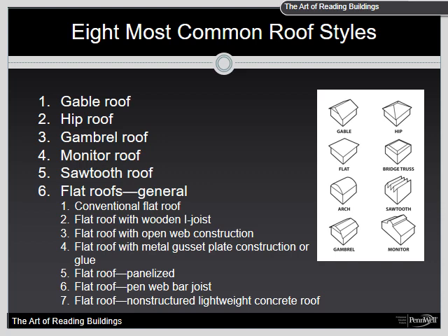Monitor roofs. Monitor roofs have customarily been used on barns and some commercial buildings, but their design affords many advantages for a wide variety of buildings such as garages, dwellings, and some other buildings, hence their growing popularity. A monitor roof is basically composed of two shed-type roofs that are separated by a center section that is raised above the shed roofs and supports a gable roof. The raised center section is customarily flanked by windows or eave lights along the sides for daylight and ventilation.